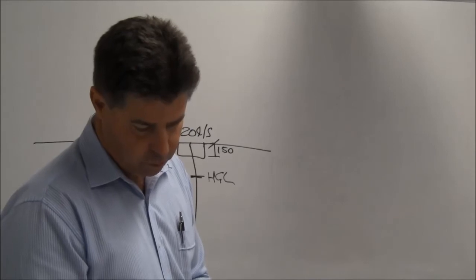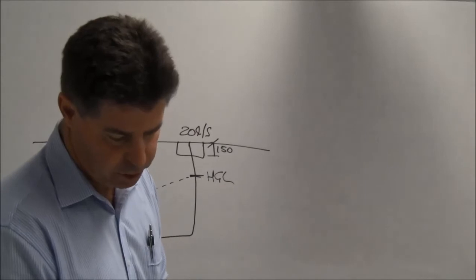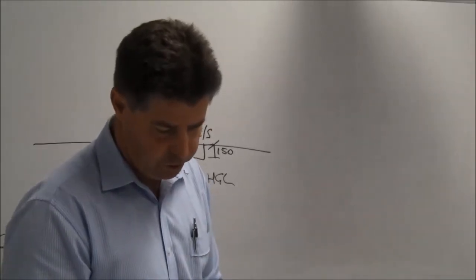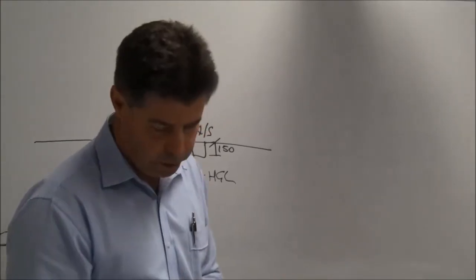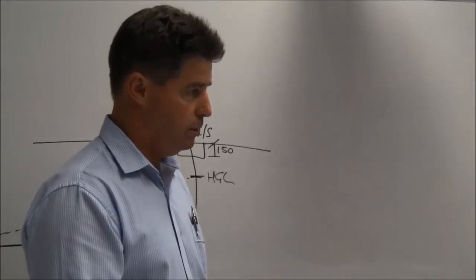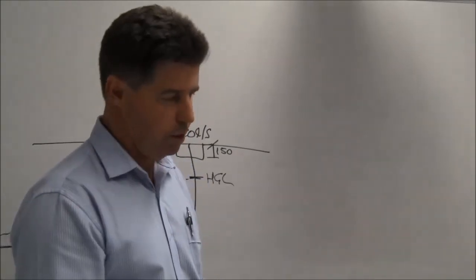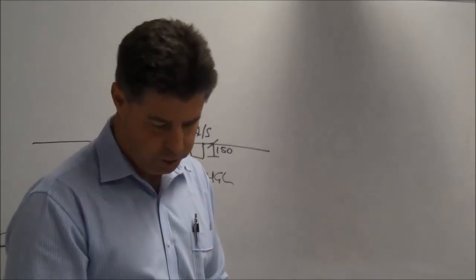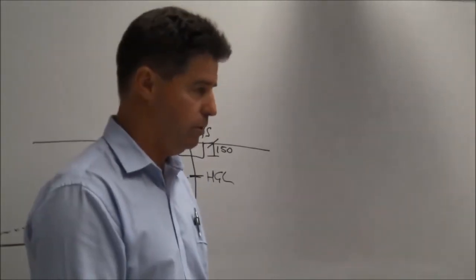Where did the 2.42 come from? From that formula, the one above it, equation 2.12. Oh, okay, right. And then to find the actual friction head, which is that hydraulic grade line head, all we're doing is multiplying the friction slope by whatever length of pipe it is. So the friction slope on that particular pipe for that flow rate at 2.42 multiplied by our length gives us a head loss in that pipe of 532 mil.